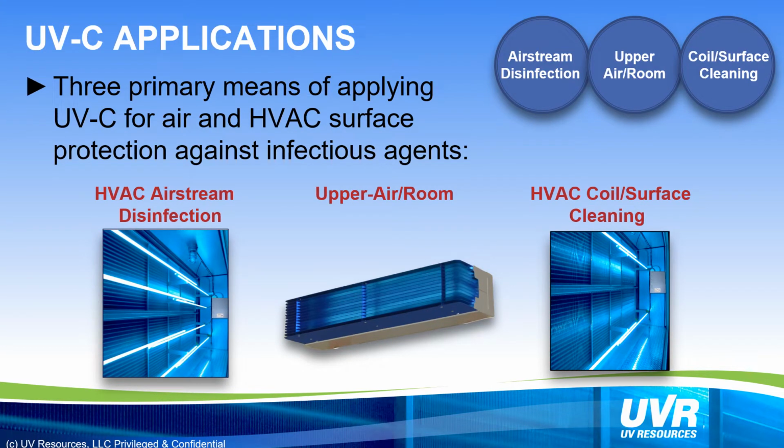There are 3 primary means of applying UVC against infectious agents: HVAC airstream disinfection systems, upper room or upper air luminaries, and HVAC coil-surface irradiation systems.